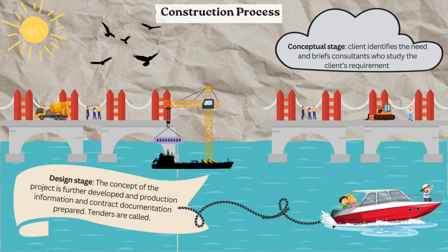Secondly, a building project begins to take shape during the detailed design and tender stage. The design is completed at this point, and the purchase of materials and design services begins. Construction contracts are either put out to bid or a construction contractor is chosen. The aim is to keep the design team informed about the procurement process and to be prepared to submit the final design to the owner at the end of the